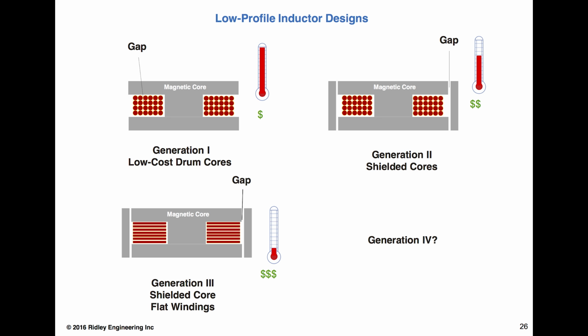When they were back at 60 hertz doing 10 megawatts, everything we know about high-frequency magnetics today was done back then, because that was high-frequency magnetics. They had the skin problems, core loss problems, proximity loss problems, and they came up with flat helical windings, different shapes, and made sure the gap was well away from the windings. All the things we're rediscovering at 10 megahertz, they knew back then at 60 hertz. So there's always this power frequency curve.